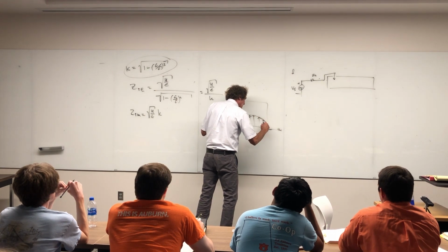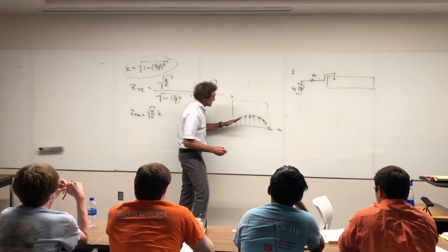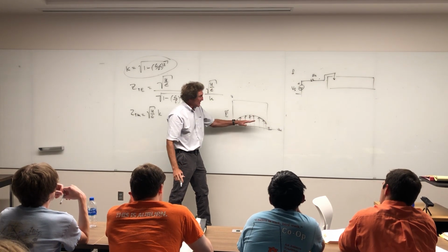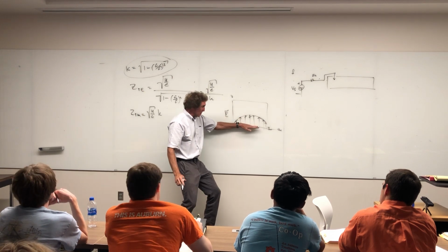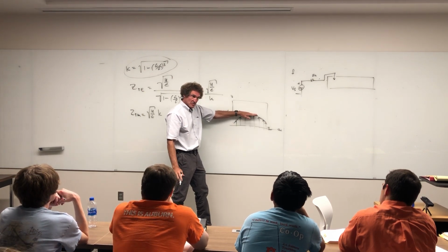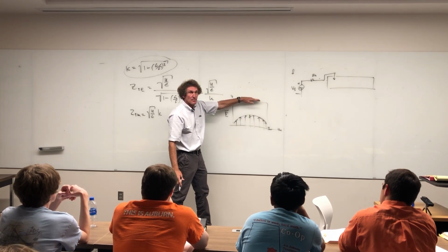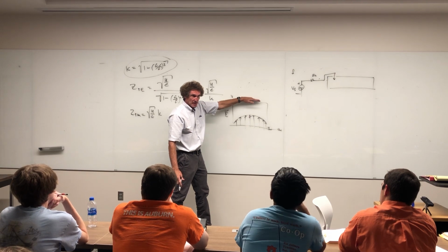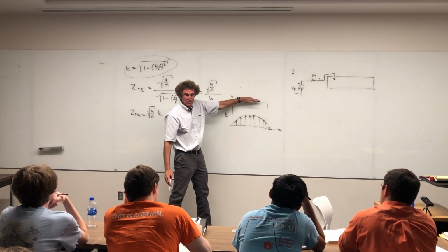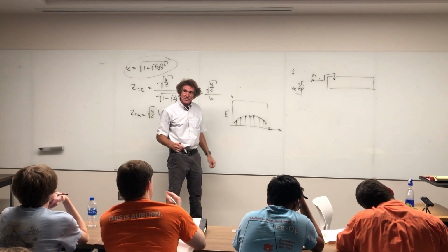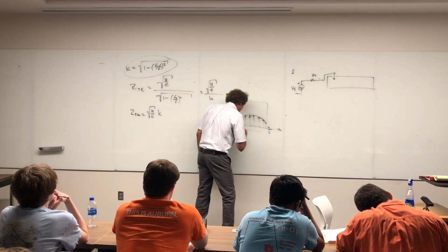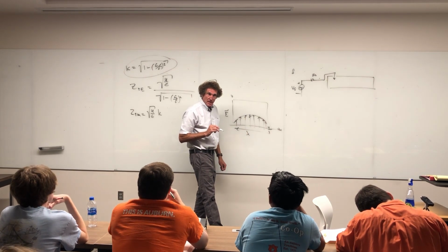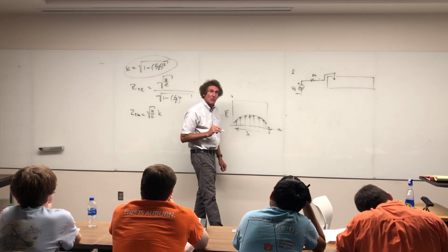Now, this is hard for me to draw correctly. We'll go right to 0. But you see how that field pattern, this would be the E field I'm trying to show you in terms of picture. And that same field pattern would be at the very bottom here, right in the middle where y is equal to, say, b over 2, and right at the top. Follow me on this? It will not vary with y, but it varies only with x. Can you all see what I'm talking about here? That's a TE10 mode. That energy propagates. Something to note here. You'll notice this is exactly a half wavelength. You all see that right there? That's a half wavelength. And that's the way it will always be.